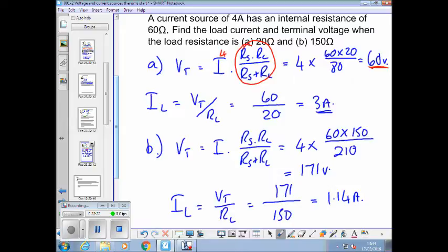And remember from our work already, when do we get the most power transfer from one to the other? Matching impedances. When we match. And that would be true with the current source or the voltage source, is when we match the load to the internal impedance of the source. You're still looking confused, Carl? No, I'm just working on it.